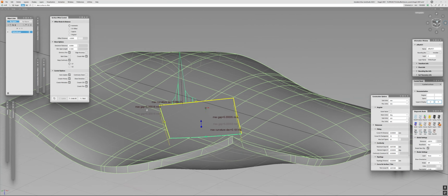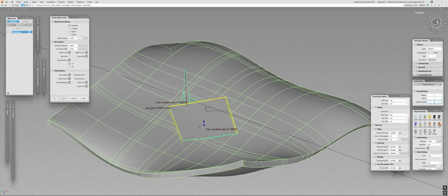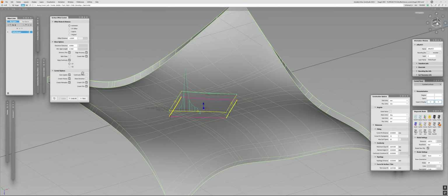Okay, the last thing which we can try is the option called edge accuracy. I already said that the edge accuracy will take the same deviation, but for the edges. So for all of these edges, from the true edges of this patch. Not the one that was stripped, but the one which is sitting on top of that. Kind of our last resort. Well, let's try. And as you're going to see, it didn't really help us much. So basically nothing really happened. Nothing good happened at all.